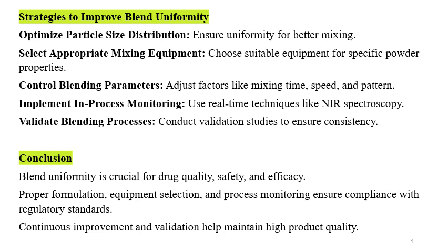Validate blending processes. Whenever you are going for scale up from lab scale, you should perform all the activities for blend uniformity, like checking and studying various fill levels, testing for the blend uniformity, blend assay, testing for the content uniformity and assay, and also different blending times and blender speeds can be evaluated.